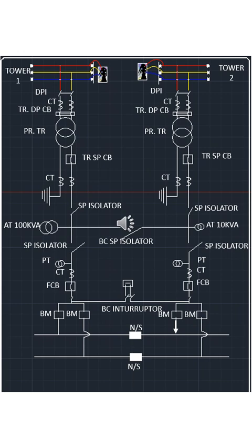So after transmitting the power through the transmission line at high voltage, we are stepping it down to 25 kV or 2 into 25 kV. Generation is generally three phase, red, yellow, blue, and with the use of transmission towers, we are receiving it in the traction substation.